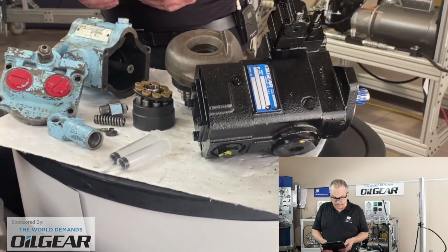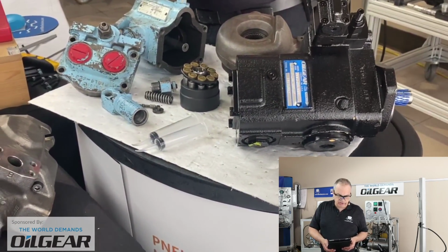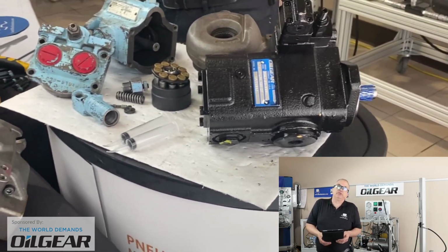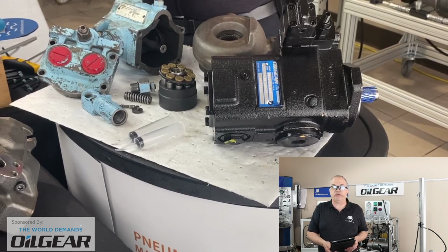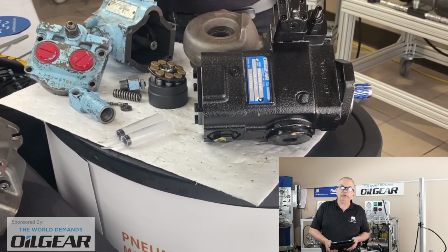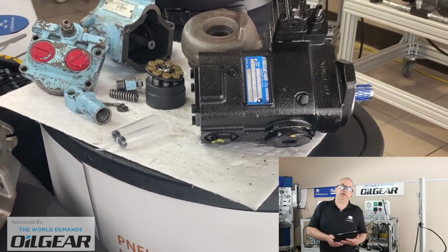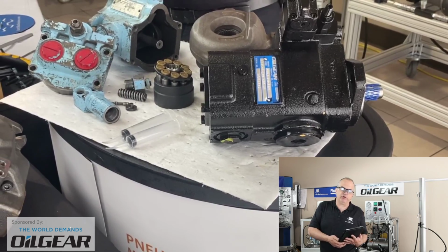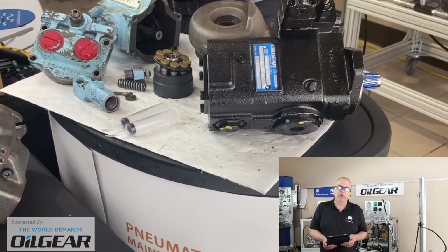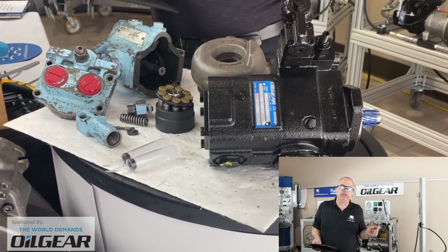Jalal asks, he's asking about the best adjustable. How much should be the difference between the compensator and the relief valve? Yeah, Jalal, it tends to vary from system to system. So the steepness of that line in the active region is a factor, as is the override value for a relief valve. So typically you want to have a little bit of separation there